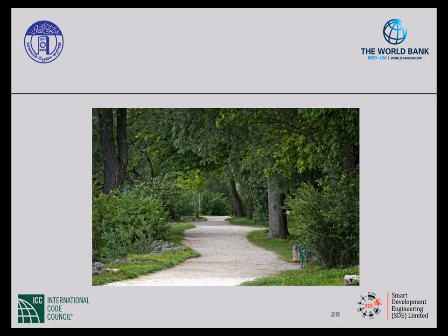So what about this footpath? Do you think it's accessible? Let's check. It is constructed of gravel, but could gravel be accessible? And the answer to that is yes. It is accessible provided that the slope is compliant, which we'll talk about in later slides. The gravel has been compacted and is not loose, so this fits the criteria of firm, even, slip-resistant, and stable.